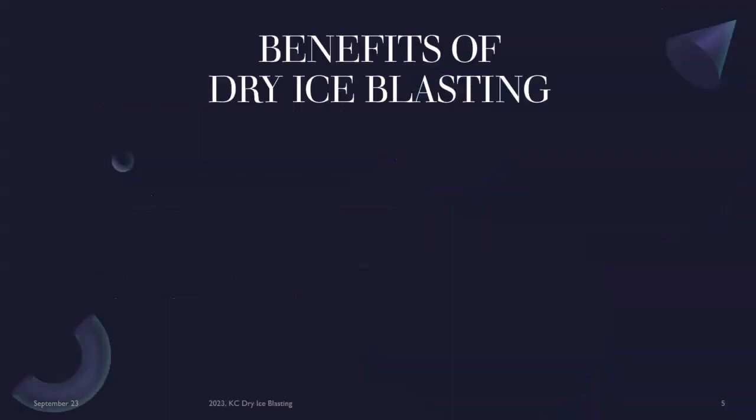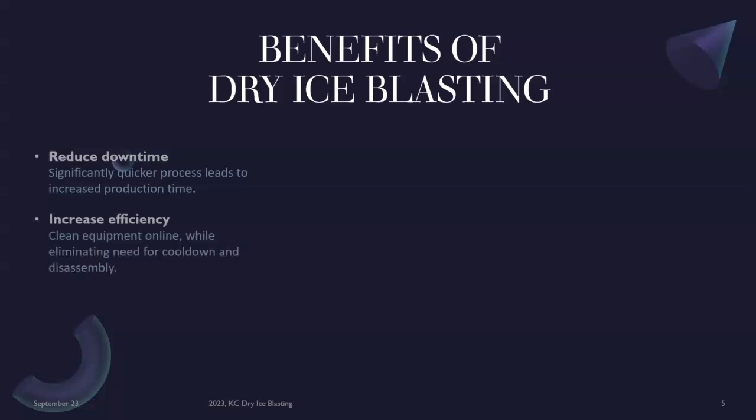The benefits of dry ice blasting: it reduces downtime. It does not take as long to clean the machinery as by hand with solvents, which is labor intensive and dangerous to the people that are using the solvents. Increases efficiency. It speeds up the production by cleaning the pulleys, embedded nuts and bolts, screws, different items that you would not be able to clean by hand or other cleaning methods.